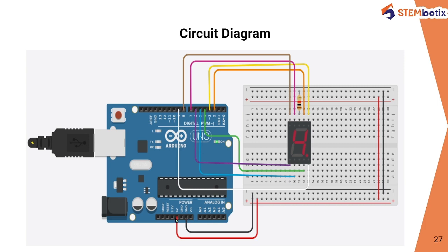So we have connected the Arduino Uno to the breadboard. Now this is the negative rail, meaning ground, and this is the positive connection. From here, extend the positive terminal to here, and similarly the negative terminal is extended to here also. So similarly here is the ground connection and here is the positive connection. Now it's time to connect the different pins of the 7 segment display to the Arduino Uno board in order to control its turning on and turning off process.